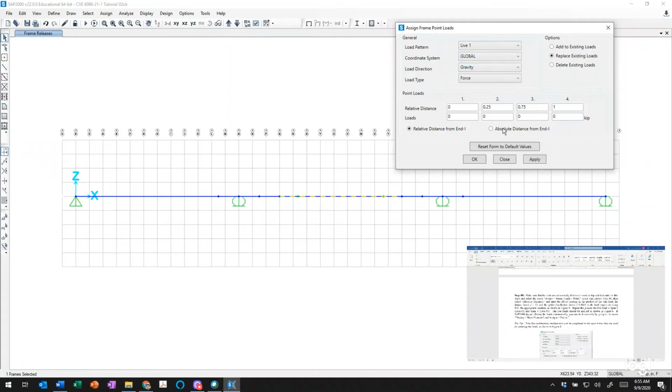So I'm going to use absolute distances. And so in this case, I would want a distance. Let's see, that member is 45 feet long. It's 15 feet off each end. It was originally 75. So minus 30 gives me 45. So 45 divided by 2 is 22.5, and I want to go minus 14 feet from there. Got to watch units though. So let's see if I go to feet here. Yep. All right, so you converted the number for me.